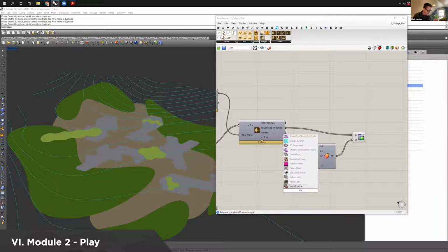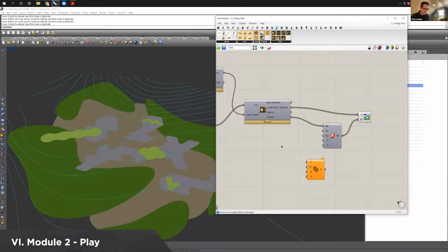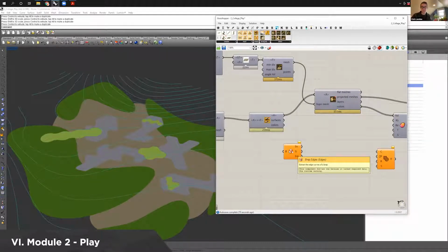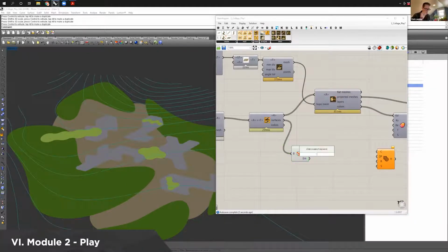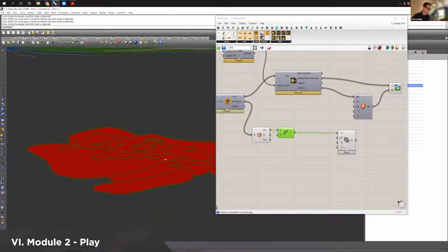All right, we're going to make hatches. Now this is using the Elefront plugin, but what we'll do is we'll turn these into curves. Or no, sorry, I keep doing that too. We're going to do brep edges. Now a brep is a surface or a poly surface, anything that's surface based. So we plug our surfaces that were coming out of the collage into here. We join the curves, any of the curves that were the naked edges, those are the naked edges. And then we plug those in and we have hatches. The default is solid hatches.